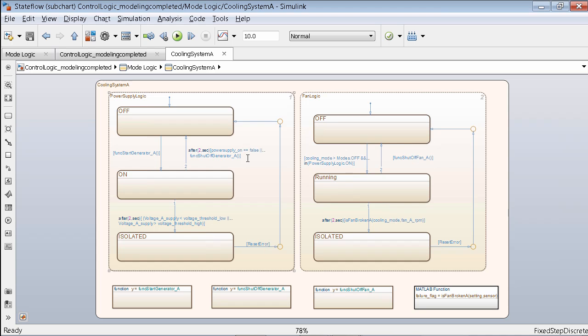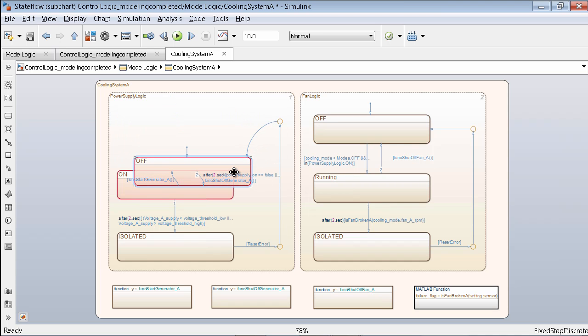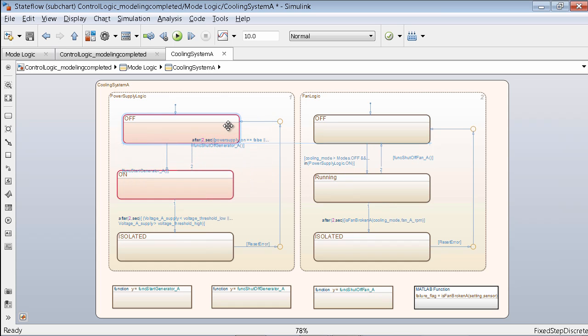So there is the editor, along with providing, as I said, a canvas to draw it, it also provides some edit time checks for you. So let's say you were to mistakenly have some semantic errors by drawing one state over the other, or the states weren't properly aligned. This would automatically get flagged to you, as I'm showing you over here in Stateflow as red. But you would also have lines to help you align these objects and make sure that the objects are aligning up as they should. So there are other static and runtime checks that are provided with the tool.